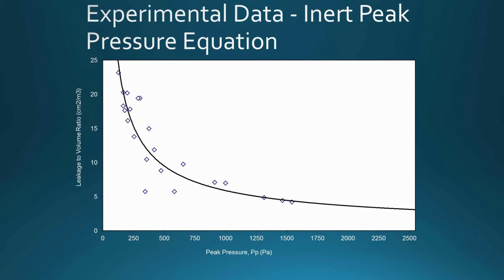So no matter how many discharges we did into that enclosure, we pretty much always verified the one point on the curve. What we did that was different here was that we did it over a wide range of enclosure leakages, all the way from, let's say, an 8-minute retention time to a 30-minute retention time and different enclosure heights.